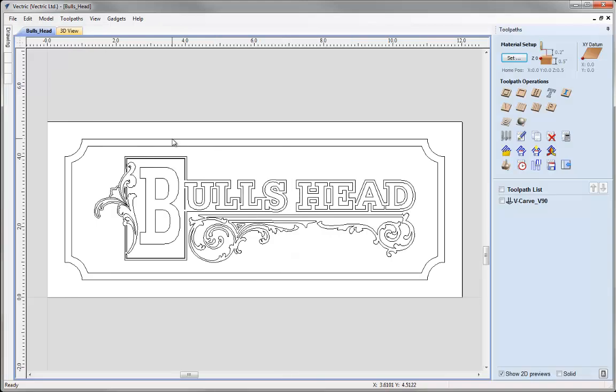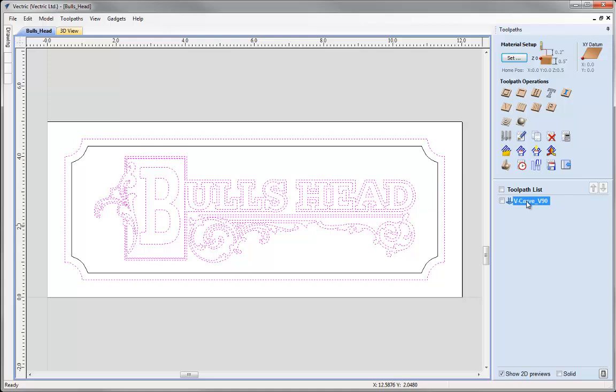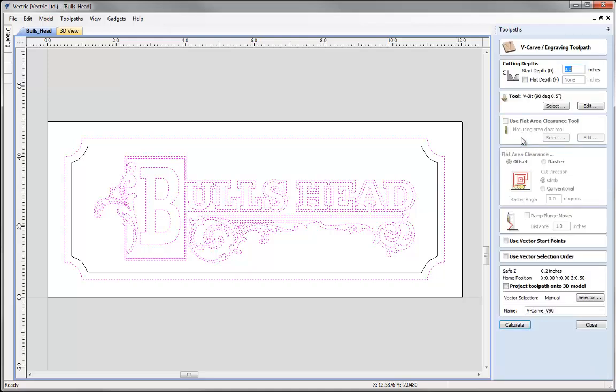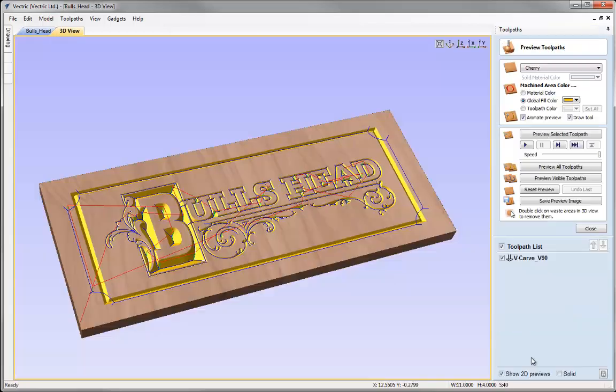to the Toolpaths tab, and to reapply this toolpath is as simple as selecting it, clicking on the icon here to edit it, and you can see there that we have created a new vector that wasn't previously in the selection for this toolpath. So now what I want to do is just hold shift down and click on that vector there. The other vectors that are still available have been reselected, but holding shift and clicking that will add it to the selection. I'm going to take the same values we used before, hit calculate.